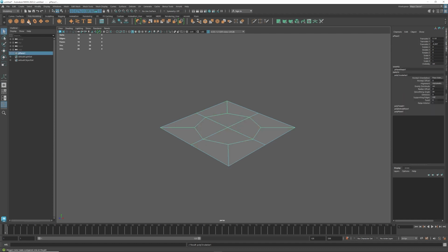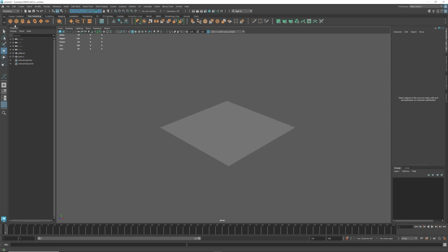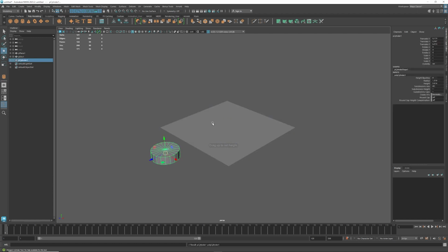And just to create a good size with that, I'm going to go here, and I'm going to create just this little hunk here, and the radius for that is basically 2.4 millimeters, so 2.4, and the height is going to be 1.8. So that is my ultimate size here.